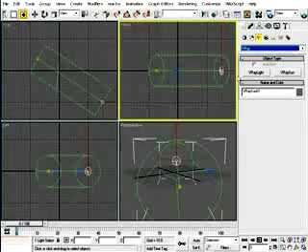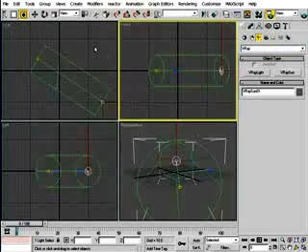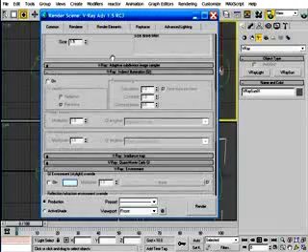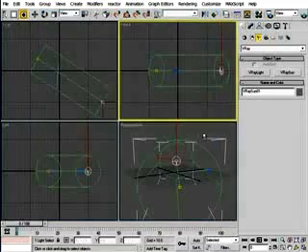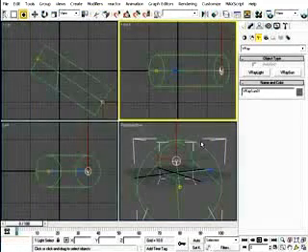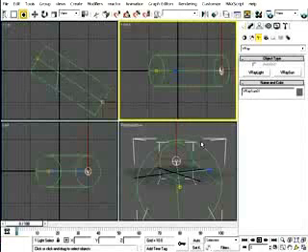So another example besides the VRay Sun is linear color mapping. Color mapping is like exposure control, but since the VRay Physical Camera has exposure control built into it, you shouldn't compound or exacerbate this effect by using additional exposure control, i.e. color mapping. By leaving the color mapping feature set to linear with its default values, you're technically using exposure control, but linear essentially has a neutral effect. So I recommend setting color mapping to linear when using the VRay physical camera.